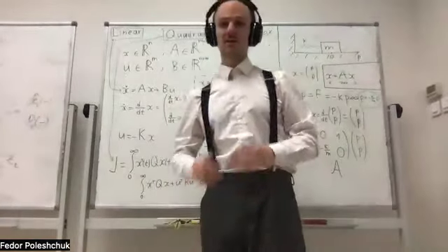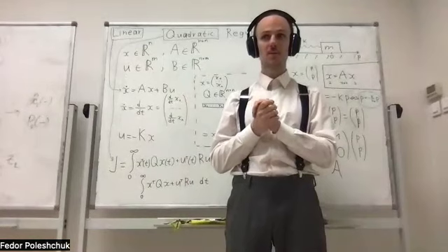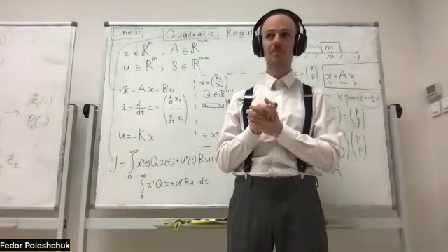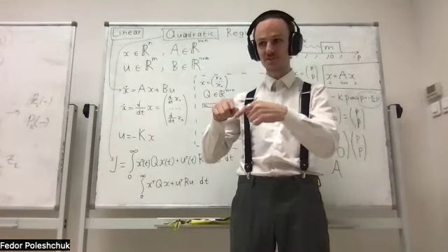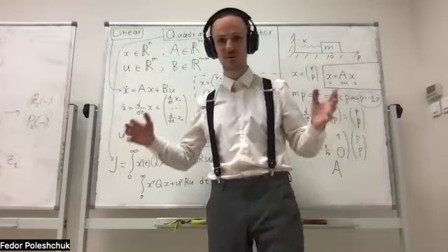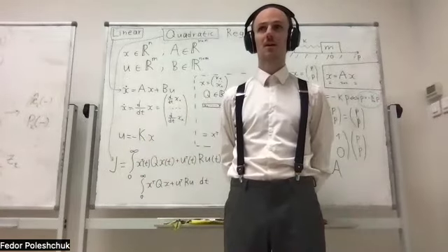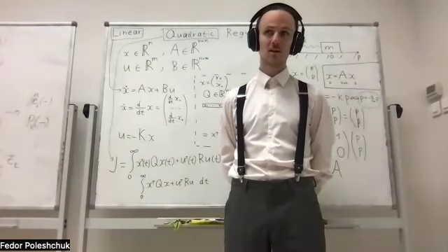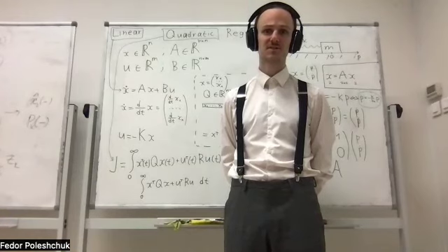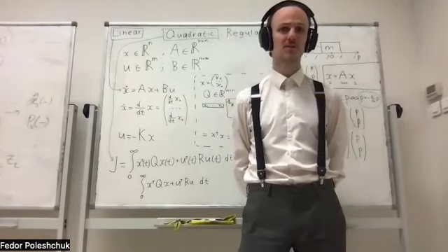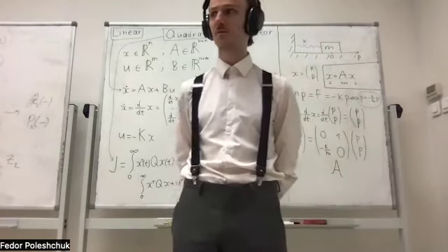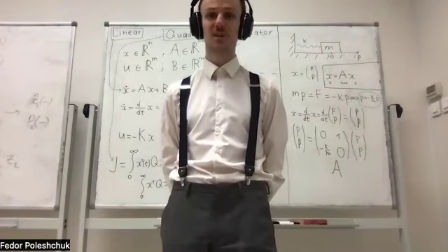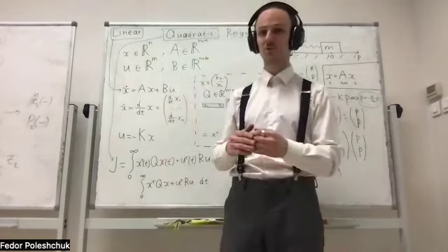what I have to say is that on different levels of control, very different approaches are used. Why so? Because let's imagine that you are planning ahead a series of passes and kicks. So the robots have to pass the ball somehow. And this planning ahead could be up to, I don't know, 20 seconds or something. The scheduler of our robots, the control loop, runs with a frequency of around 180 times per second. So it will be an enormous horizon.